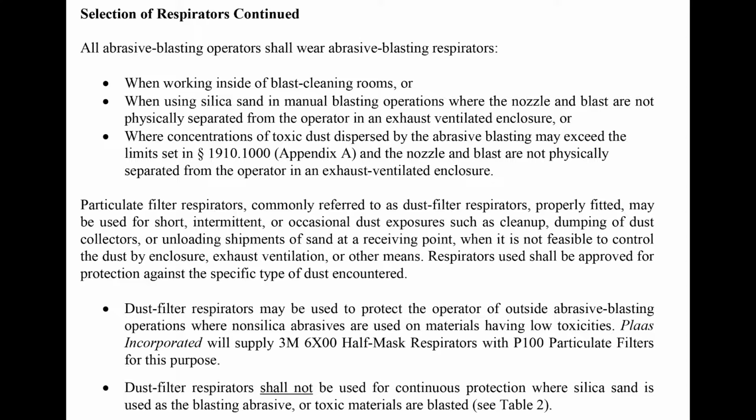Particulate filter respirators, commonly referred to as dust filter respirators, properly fitted, may be used for short, intermittent, or occasional dust exposure, such as cleanup, dumping of dust collectors, or unloading shipments of sand at a receiving point where it is not feasible to control the dust by enclosure, exhaust ventilation, or other means. Respirators used shall be approved for protection against a specific type of dust encountered. Dust filter respirators may be used to protect the operator of outside abrasive blasting operations where non-silica abrasives are used on materials having low toxicities.